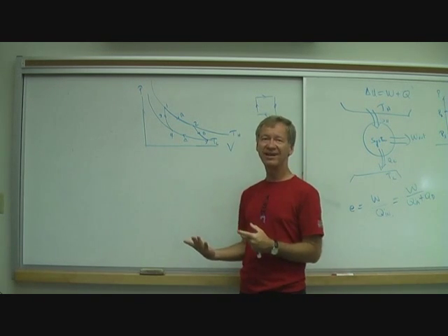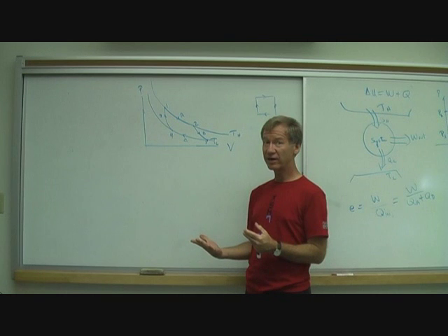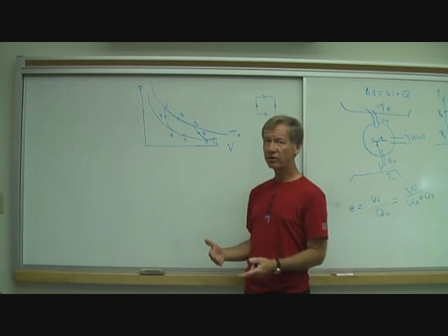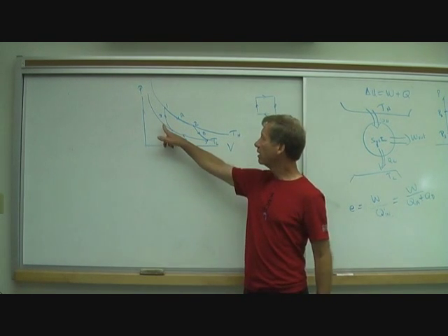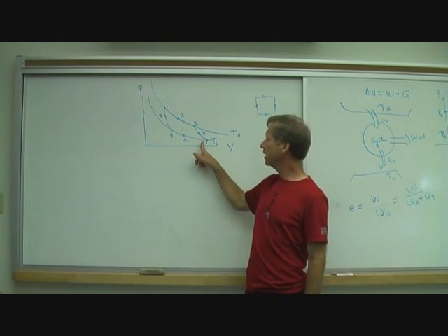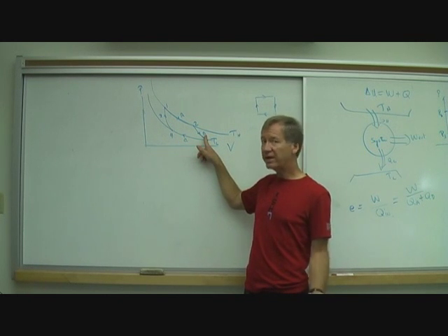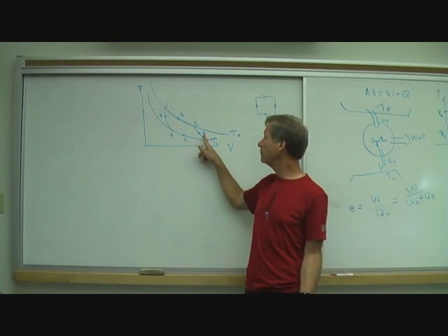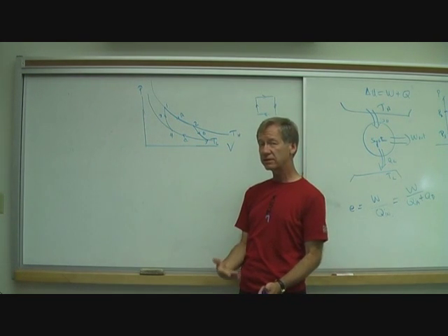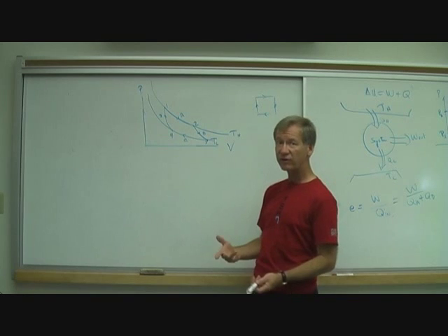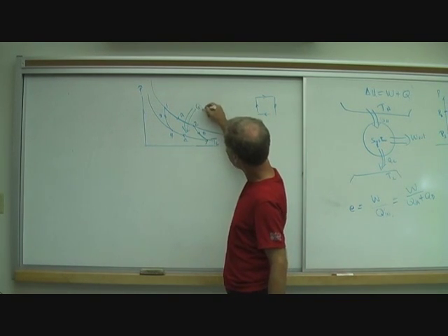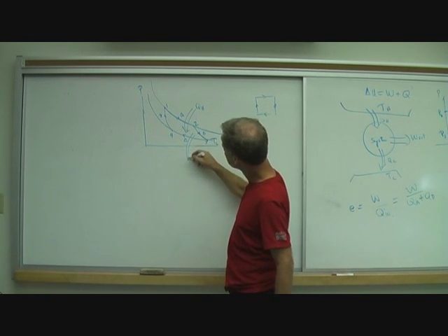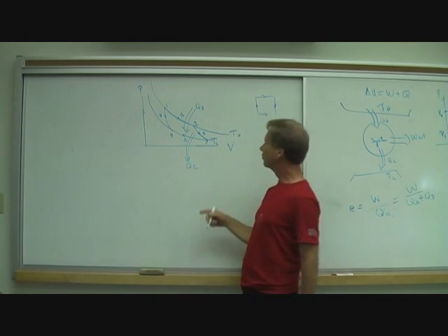The heat flow for 2 of these is pretty easy, right? Remember, adiabats have no heat flow. So this one and this one have no heat flow, all right? Well, that must mean one of these is an innie and one of these others is an outie. And you can see fairly easily that here is my QH and here is my QC, right?